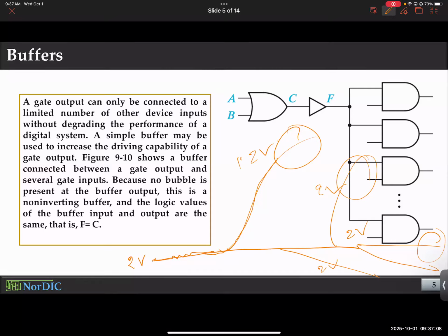Sometimes it will be 1.2, sometimes it will be 1.8, sometimes it will be 1.6, it will be all over the place. So it creates a challenge, a nightmare essentially, for the circuit designers. If you design your circuit for 2 volt supply voltage, you expect to have 2 volt, but you get 1.8, 1.6, your circuits will just be messed up. I mean, the more I tell you this information, you feel like, how do things even work? They shouldn't even work at all, right?